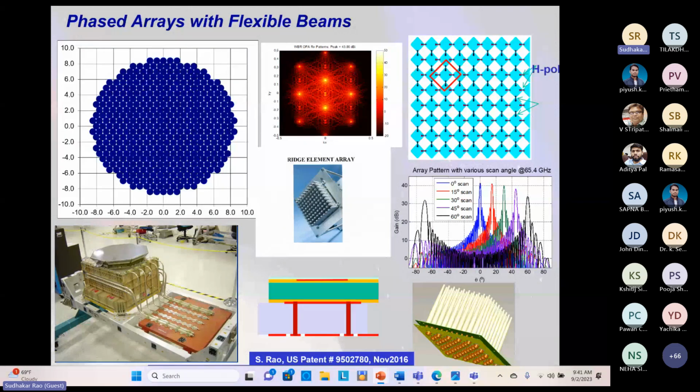So these are some phased array hardware you have seen. Different types: on the right, it's a bow tie type element. In the middle, you see a rigid element array. On the bottom are the stacked patches. And then on the right side, you can see conical Vivaldi. That provides 1 gigahertz to 18 gigahertz frequency, a very wide, ultra wideband spectrum.